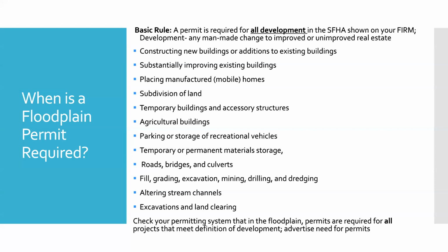So when do we need a permit? The basic rule is that all development in the special flood hazard area, which is defined as any man-made change to improved or unimproved real estate, is going to need a permit. So of course that means constructing new buildings and substantially improving existing structures, but it also means putting in subdivisions or roads, bridges, culverts, anything, filling, grading, excavation, mining. So it's not just building, but really any kind of change. So check in your permit setting that permits are required for all projects that meet the definition of development.